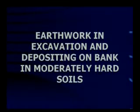Earthwork in excavation and depositing on bank in moderately hard soils. Where do we have to excavate? The first thing would be under the head walls. You need to excavate under the head walls. The next excavation would be required under the pipe. Before you fix the pipe in position, you have to lay a thick layer of granular material so that the pipe is in position. Where else do you need an excavation? You need to excavate under the apron on the upstream side and the downstream side. Is that okay? Now we'll move on to the next slide.